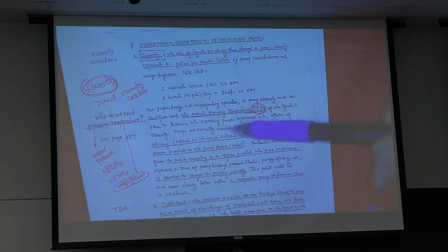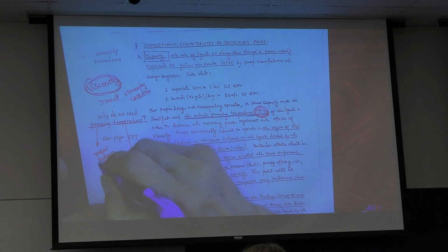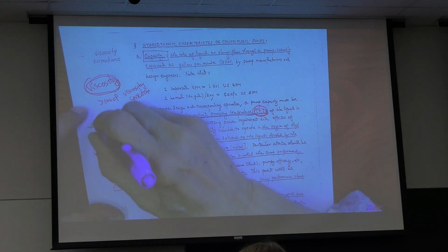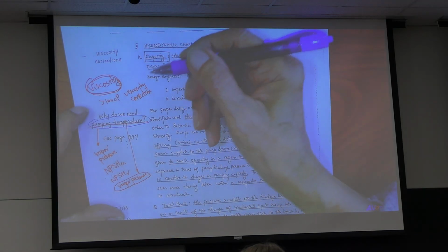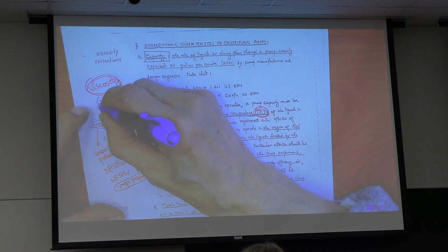So, if somebody asks you to size a pump, don't accept the job so quickly. Can you tell me the pumping temperature? What is the viscosity of your liquid?